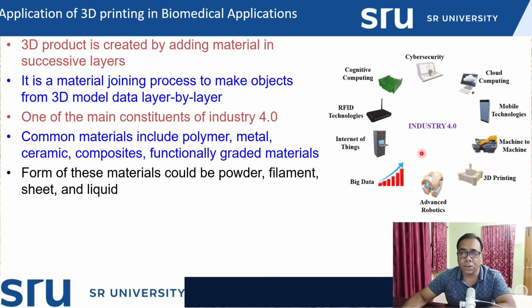Additive manufacturing technologies are used, like in an FDM machine. In an FDM machine we use wire filament. The filament passes through the nozzle, and in the nozzle itself a heating element melts, or partially melts, the filament material. From the extruder the material comes out, and then it is printed or deposited on the print bed layer upon layer.